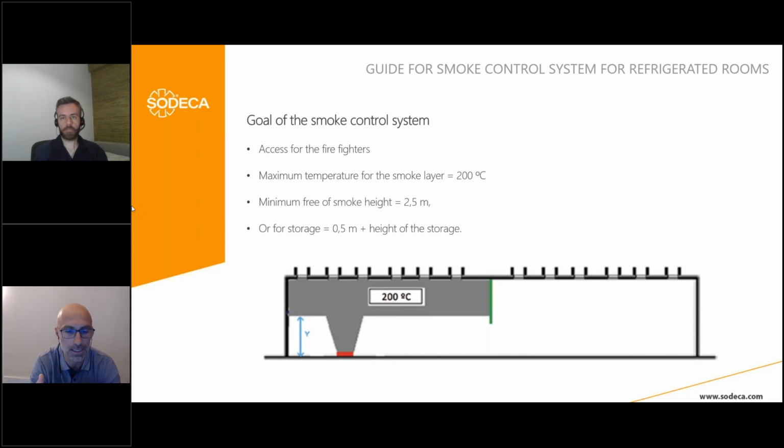You can see it in the BS 7346-4, in the British standard, in the European technical report, the TR 12101-5, for instance, or in the Spanish standard UNE 23585. Typical, you can see it in these smoke control standards based on buoyancy using steady state fires.